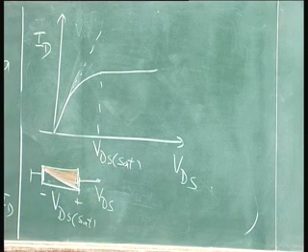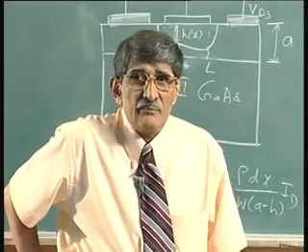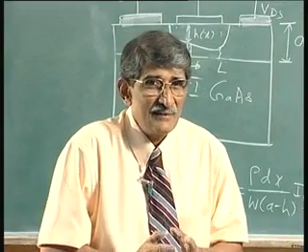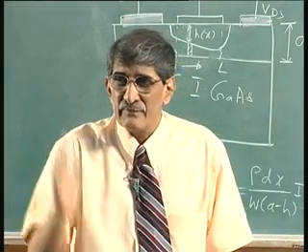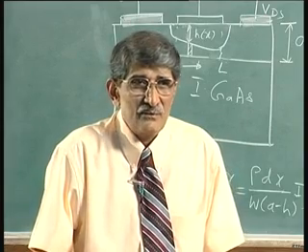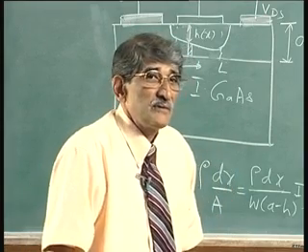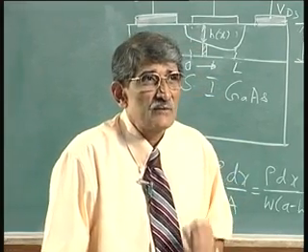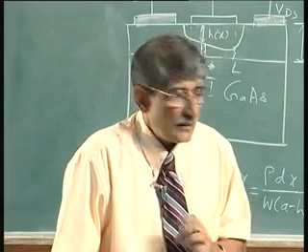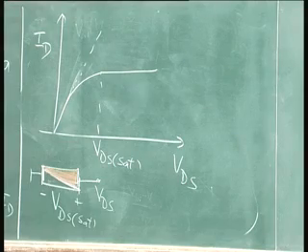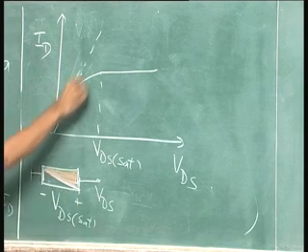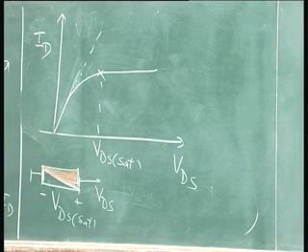So, that is the entire concept involved in the IV characteristics of the MESFET, and the model that we have discussed is the Shockley model, because Shockley was the Nobel laureate who first gave it way back in 1952 or so. That model still holds good very well, so long as the channel lengths are not too short. We do not deal with short channel lengths here. Now what we want to know is, how much is the V d sat?